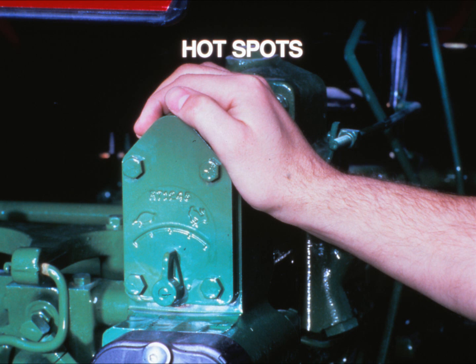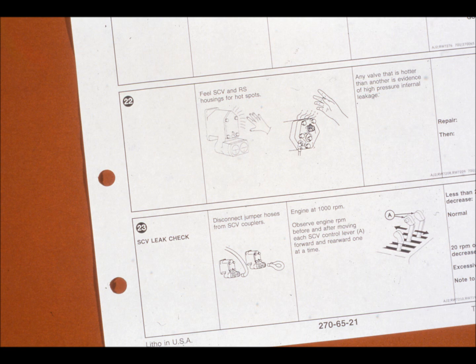Isolate the source of excessive leakage by touching the SCVs and rock shaft housings. If one valve is hotter than the others, you've identified the leak. High-pressure internal leakage creates hot spots. As you isolate problems, the diagnostic procedure may tell you to immediately repair a problem before continuing with the rest of the procedure. Or it may tell you to take note of a problem and continue with the rest of the procedure. In either case, it is extremely important to finish all tests according to directions in the procedure.